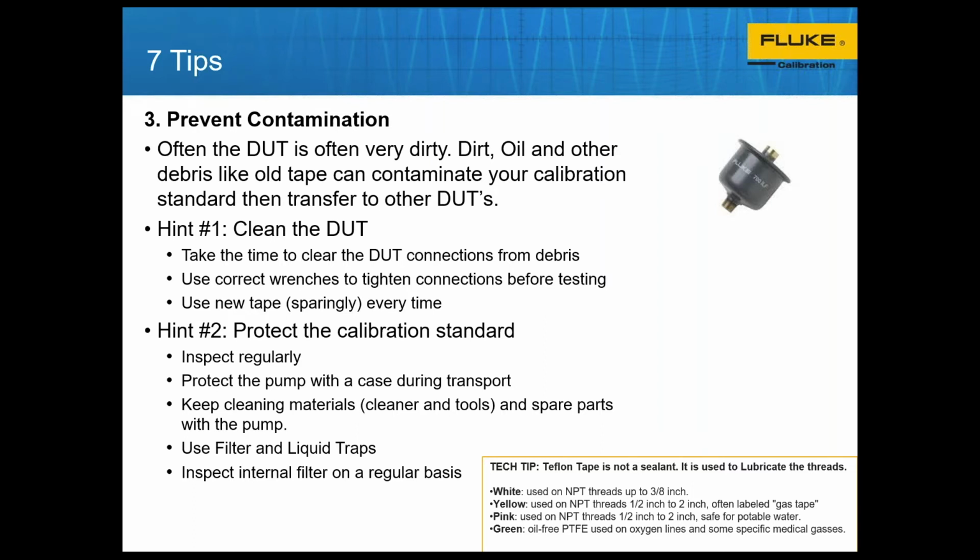And if you have any of those contaminants and you're bringing a piece of test equipment to it, it's always best to clean your device under test as much as possible. So clear the connections of debris, get rid of old tape that may have been there, take the time to clean the threads, and use the correct wrenches to tighten the connections while you're making your testing. And again, use tape sparingly.